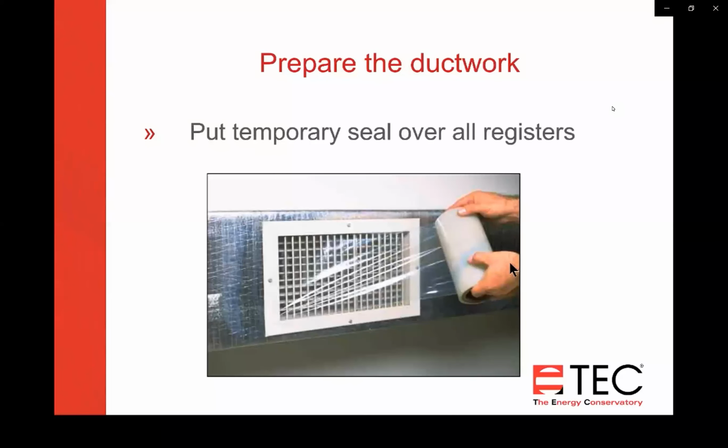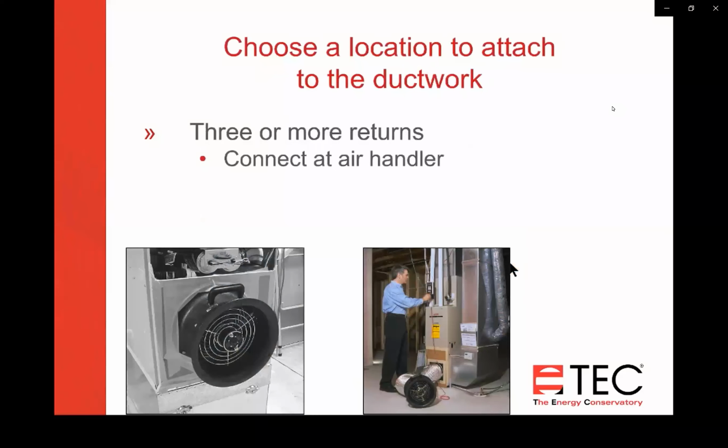You want to temporarily seal all the registers during either a total duct leakage test or duct leakage outside test. It's very important to seal over all the registers during both of those tests.